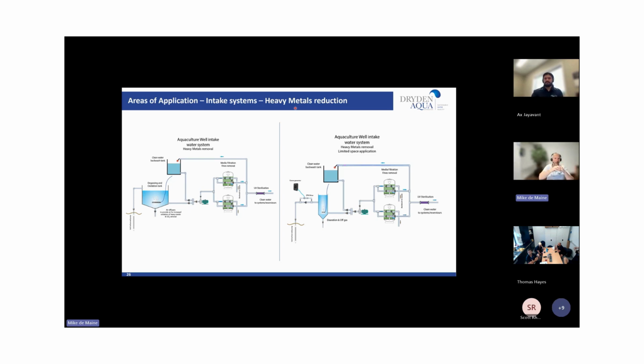When you go back into filtration, because the areas above your laterals are clean, those are the only areas that start to filter, which means that you think you're filtering at 20 meters per hour, but I've seen examples where those filters are filtering at 50 plus meters per hour, and fine organics, soft organics, you cannot remove at those high velocities.